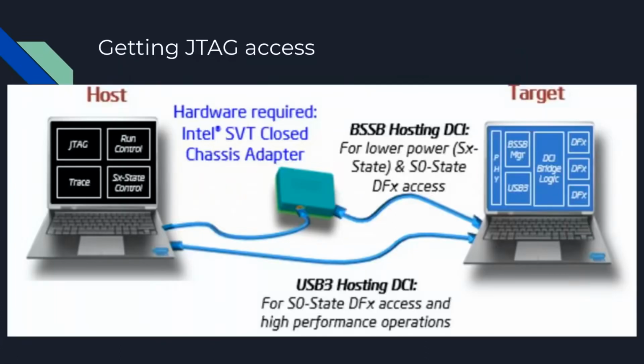And here's the great thing. Then I went to the hackerspace. I flashed it into my laptop, the image that I had just been using on the emulator. I didn't change it. I flashed it. I was like, this is never going to work, and it worked. And I've still got that image on a flash chip with me because that's what I used to actually turn on the debugger. And then you need a debug probe, because that USB-based debugging stuff that's mentioned here only works pretty late in boot, which is also why I only released the Apollo Lake stuff, because on those chipsets you can actually use this for the ME.